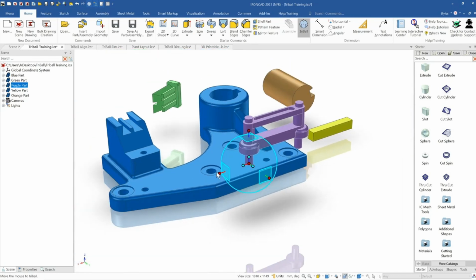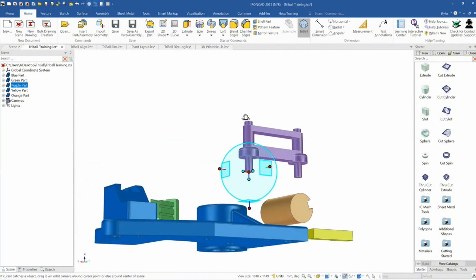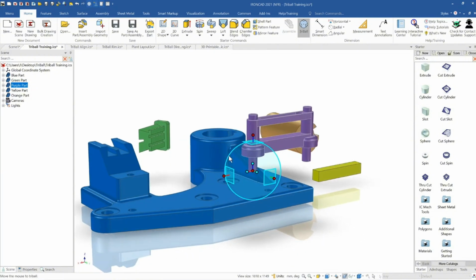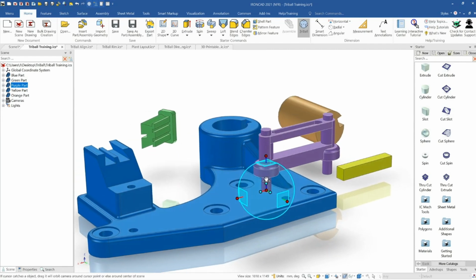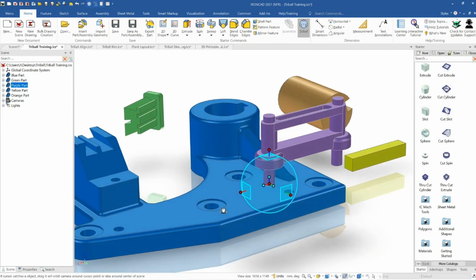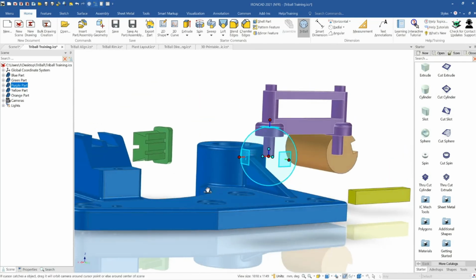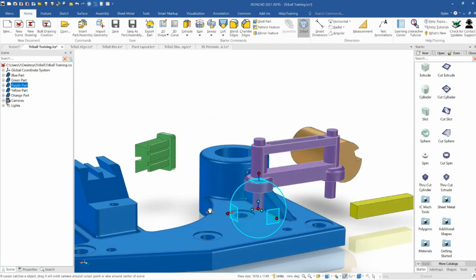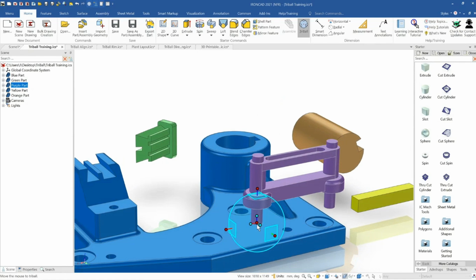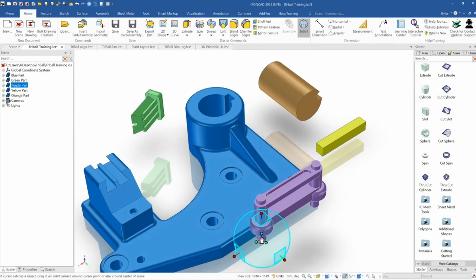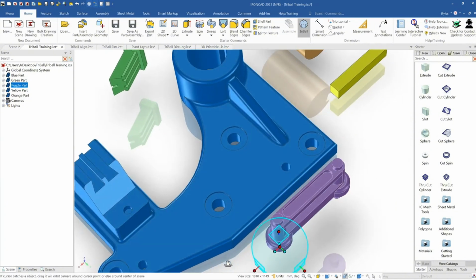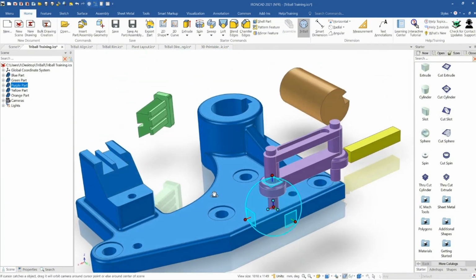Now, one thing to think about is what would you like to use as the reference for the positioning of your object? What's going to be quick? And as you get more familiar with the Triball, you get more familiar with what are good things to use as references. As we can see by where this is going to go, this part's going to sink into this part a little bit. And where we have this currently on the bottom there is not a very useful positioning area for the Triball to be in, because then we have to go and snap down there. It's a little bit harder.